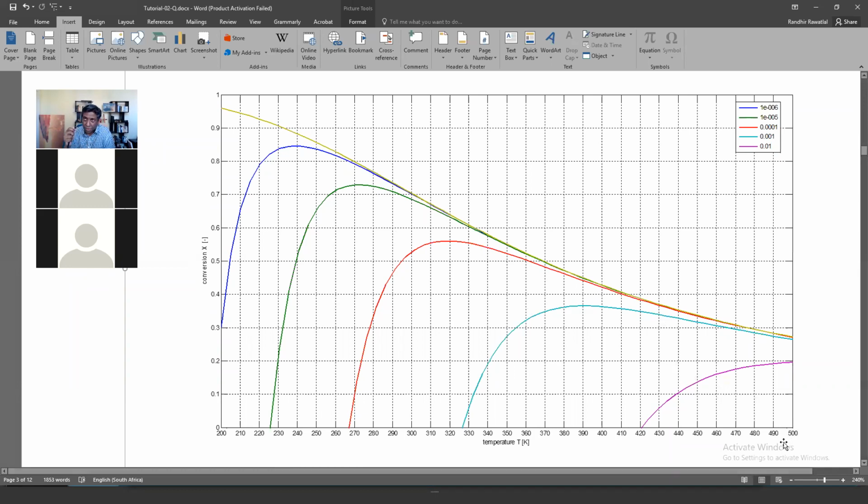By maximum rate line, we are saying we know that we have a reactor and things are going to happen there, and conversion is going to change and temperature is going to change. So as all that is happening, where would we like that to happen? We know, for example, if you start on 300 Kelvin, your temperature is going to rise or fall. So you're going to move in temperature.